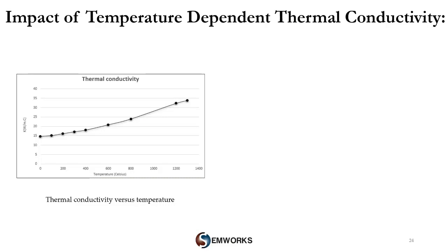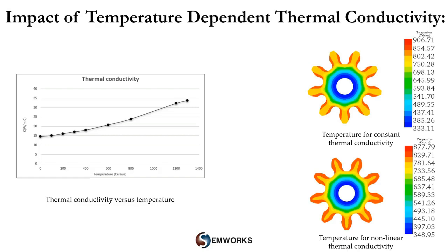For our case, we use the temperature-dependent thermal conductivity of the heated gear, and we found that the heating profile of the heated gear is more accurate and realistic, as you can see from the second figure, compared to the case of constant thermal conductivity. Now we got a well-uniform heating profile.